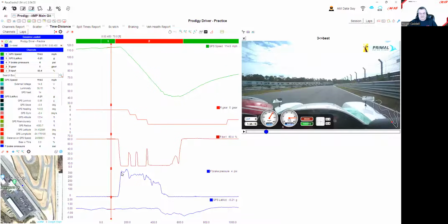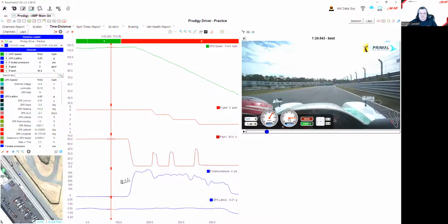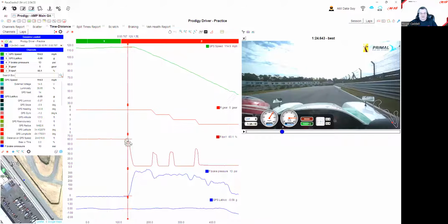Couple things that we might want to do there is, let's zoom in. One of the things you might want to do is, here's where the driver starts to release the throttle, right? We want no coasting. We want to just double check that the driver is as fast as possible getting off the throttle and to the brakes, being that aggressive, challenging the car, challenging the corner. Look how quickly the driver is coming off the throttle and how the braking is coming up. Clearly a left foot braker, using 2 feet. And we can see that, we're about 7/10 of a second past the start finish line. Start finish line is right here.